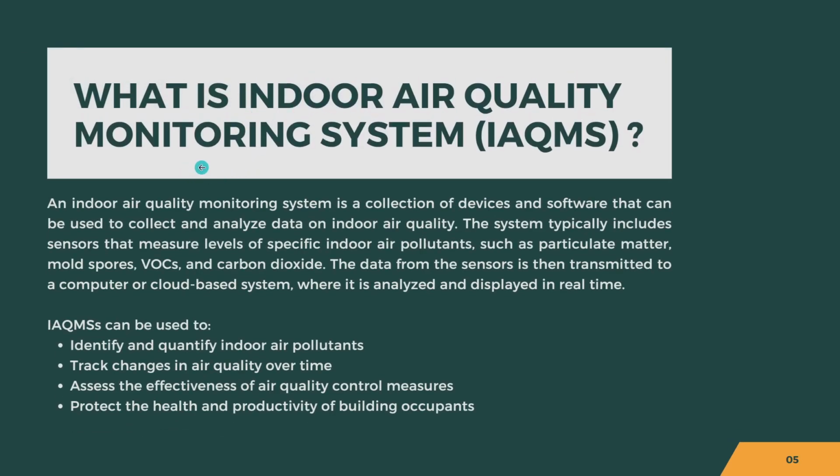So when I was assigned at STRIDE, I was given a main project from my supervisor, which is named Indoor Air Quality Monitoring System. For my main project, I was tasked to develop an indoor air quality monitoring system, which is a system to measure level of air pollutants such as CO, alcohol, propane, and so on. This system uses multiple sensors that collect and transmit the data to a computer or cloud-based system. The data is then analyzed and presented in real time.